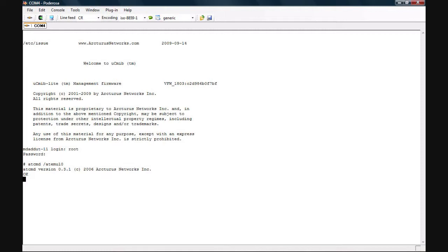So in a previous demo, I've shown you how to use GPIO SW3 to read back the IP address of the device. We can do the same thing from this command console as well. What I want to do for that is use the command ATD. If you remember from the old modem days, that would be attention dial, and then **99. And from the telephony days, **99 is a feature code, or more explicitly a vertical service code.